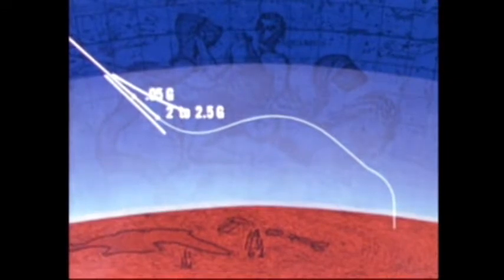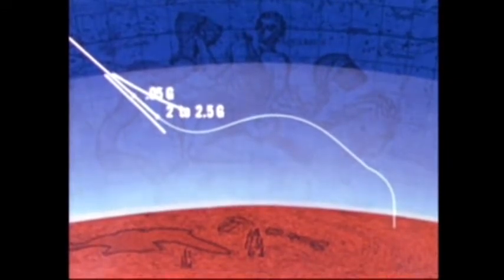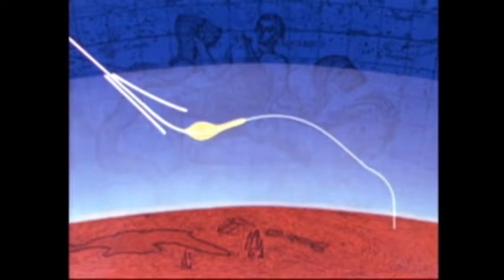The spacecraft will be in a lift-up attitude which, in the nominal case, will be maintained until the first control period. When the 2 to 2.5 G region is reached, capture is so highly probable as to be considered achieved. The spacecraft continues in a lift-up attitude until it enters the dense portion of the atmosphere. Just before pull-up, maximum G loads will be placed on the spacecraft. Just before this, the first control period begins.